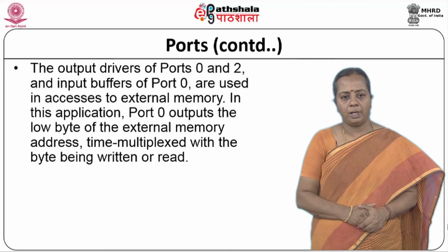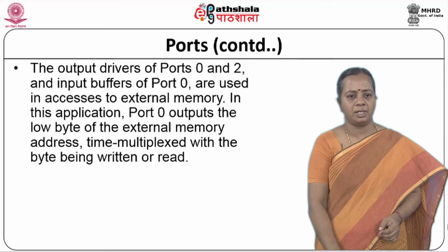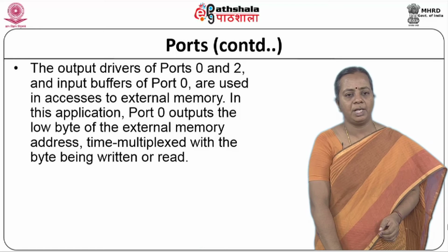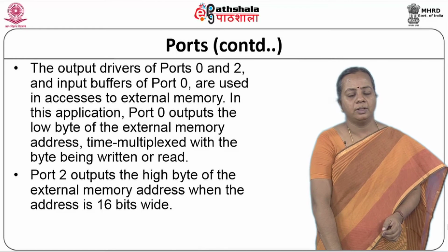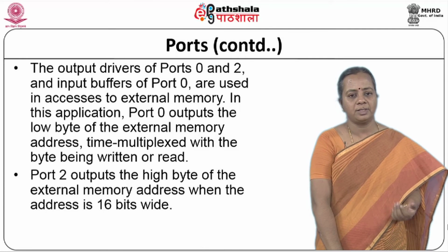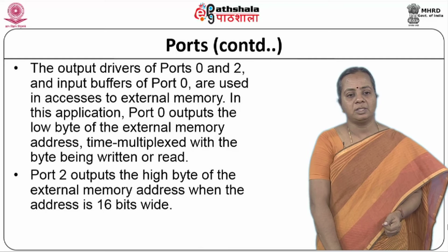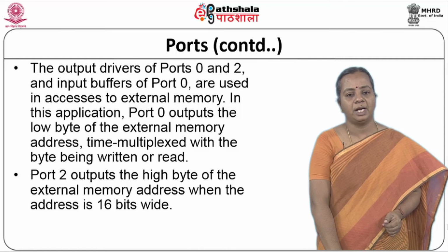The pin diagram itself gives a very good picture of the multiplexed address and data. Port 2 carries the higher byte of the external memory address. So, if I want to access a 16-bit address of a memory, then port 0 and port 2 are combined together and the address is sent.